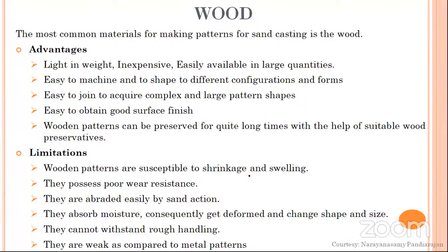So the absorption of moisture by the wood leads to dimensional inaccuracy, and sometimes it even changes shape, in the sense that when it swells, you get a different shape. So that is a major limitation of wood.